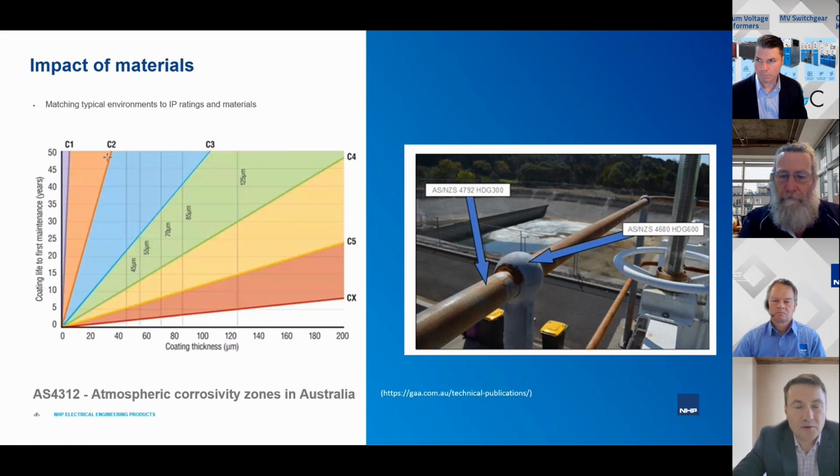But when we look more specifically into galvanized sheet metal like Galvabond, it has an even thinner layer of zinc, which, looking through all the data sheets, works out to about 20 micron, which tells us, if you look at this graph, that there's no additional protection provided by the paint or the powder coat, which is the worst case. You're looking at C3 environment as probably a suitable environment for the galvanized material, but the C4 is a lot more challenging. And in that case, our advice, being more conservative, is to upgrade to aluminium or stainless steel for the C4 environments. Okay, thanks for that, Dimitri.